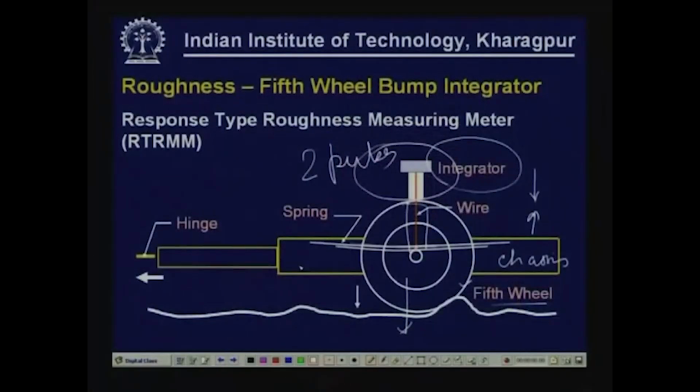So over a 5 kilometer stretch or 10 kilometer stretch, we will find out how many total inches of bumps are there. But this has to be pulled at some constant speed, and we also should be able to measure what is the distance covered by this bump integrator.